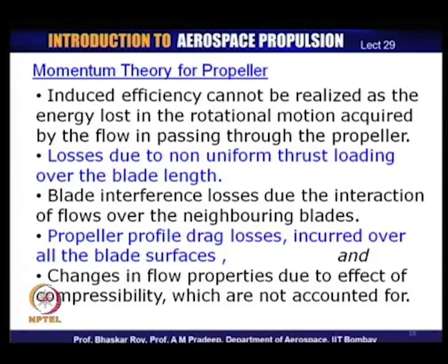Thrust is created only with the help of actual velocity change. So, the actual velocity change is what gives thrust. The rotational velocity change or rotational velocity which may appear does not contribute to the thrust creation.